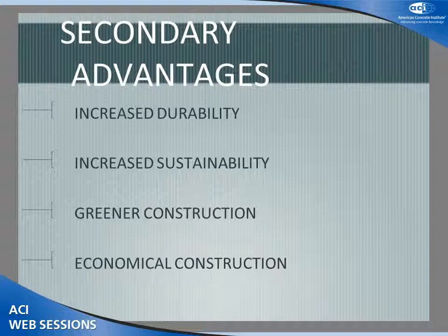Now, being a Type K cement meant that the product had to be transported from the cement mill to the concrete producer for each individual project, and being a specialty cement meant that the concrete producer would have to have project-specific handling and storage capabilities. All these factors added cost to a Type K cement project. In the early 1980s, a second product appeared on the market that eliminated or greatly reduced these cost drivers and made shrinkage-compensating concrete a more competitive construction material.